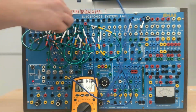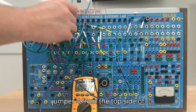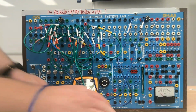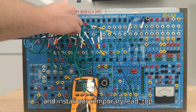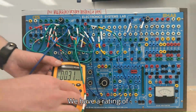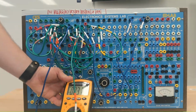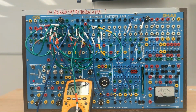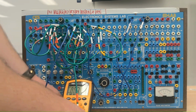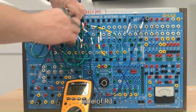We're going to intercept jumper 4 from the top side of R3. Install that into our meter and install our temporary lead, top side of R3. We have a reading of 0.31 milliamps. We're going to install jumper 4 back into our circuit. Jumper 4 goes back to the top side of R3.